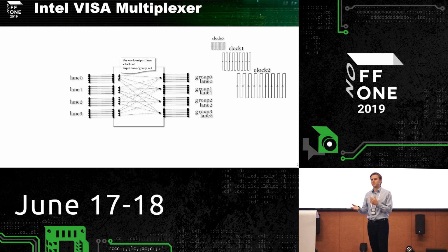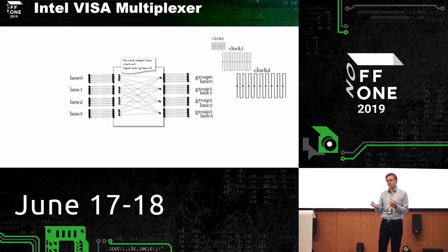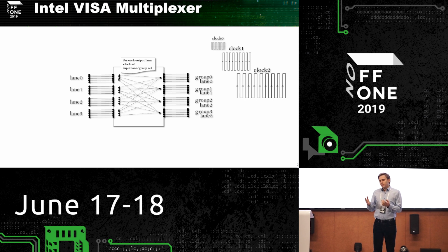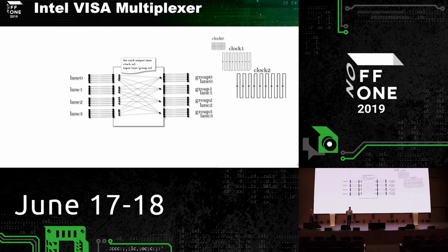But what we've seen is that very often the lines have been cut off. Even to be able to read the memory, you need to use all kinds of hacks. To read a whole address line, you have to use different hacks because they go through multiplexers,